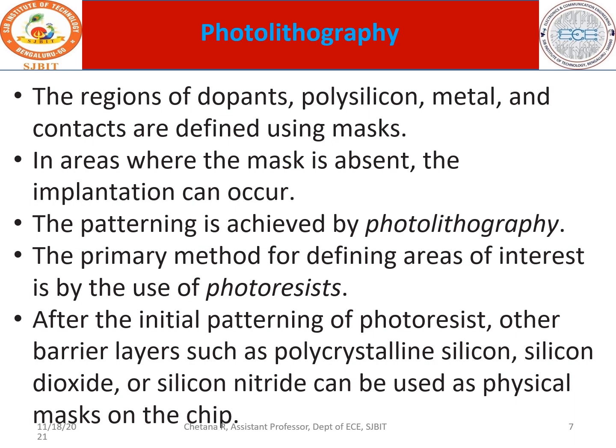Once your wafer is ready, the regions of dopants, that is diffusion, polysilicon, metal and contacts are to be defined. Since we are already familiar with the fabrication model, we have seen how the CMOS fabrication procedure is done in the N-well structure. So we know the importance of the mask.